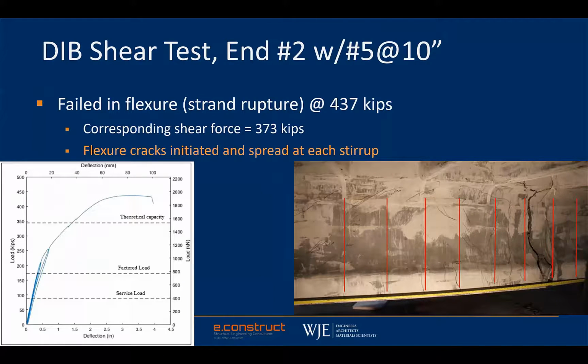The other side of the beam was also tested, and it was a bust. But you learn a lot of good lessons from something that has not worked well. The planning for this was to have the end fail in shear, but it would have stirrups in it.